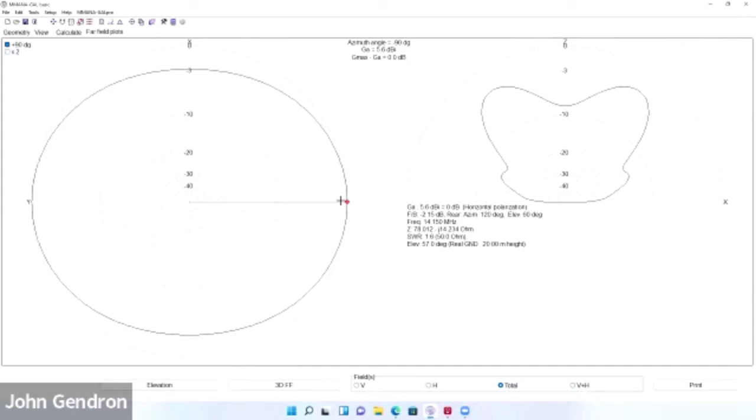Just remember that there's a couple of things with dipole antennas. When you do an inverted V on a dipole, okay, the antenna is going to be shorter than it would be for a flat top. Reason being is when you bring those ends of that wire close to the ground, you're going to pick up capacitance off the ground. So typically an inverted V is going to be 4 to 5% shorter than a standard dipole would be for a flat top.